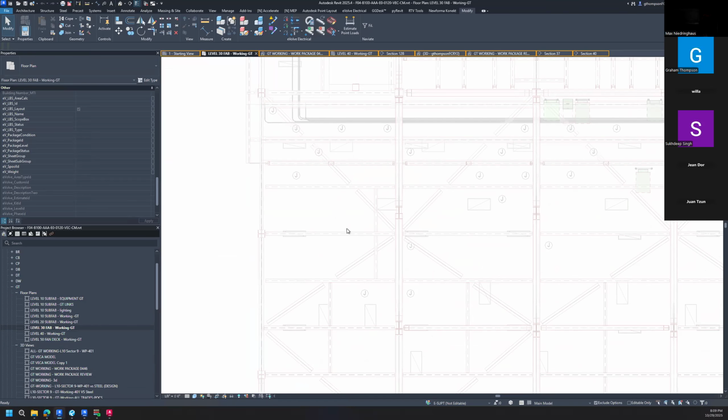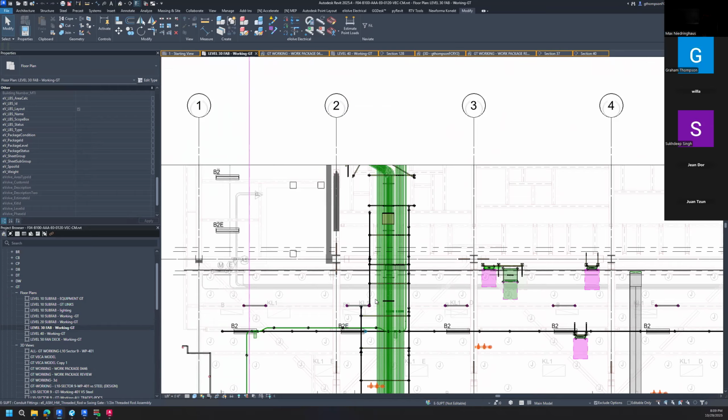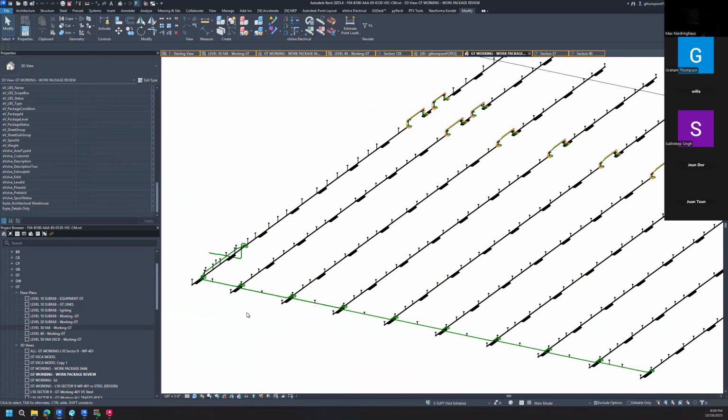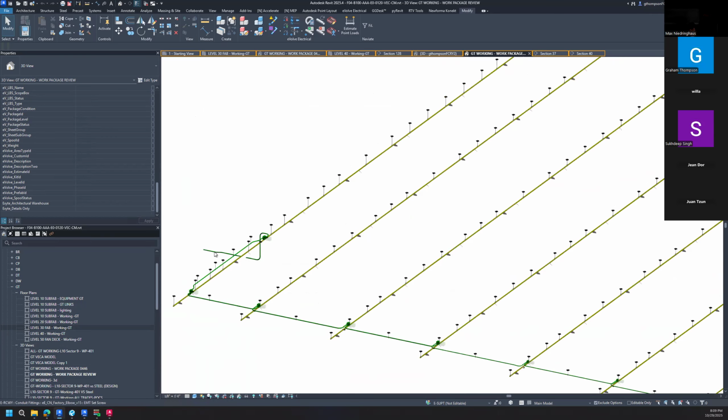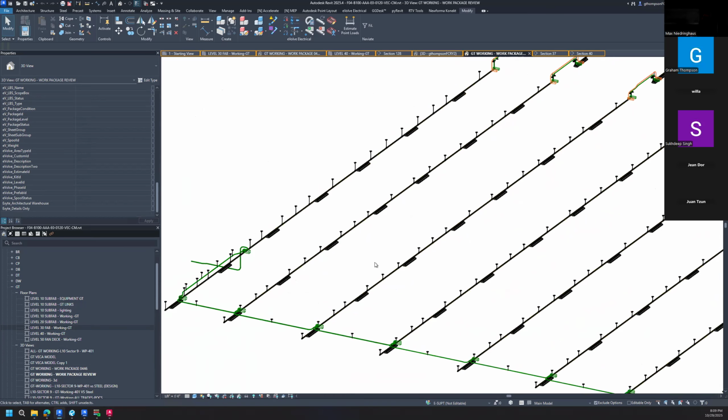And so here's my Revit portion of it. You can see all this in Revit and how it models. We use Revit to model. Navis is just a viewer. All it does is allow us to see things. Everything's just an export. So I'll go to my work package, export this, refresh it in Navis and see what happens. Did that offset move in a location that I'm no longer hitting somebody? And you just keep massaging it until you can get a product that's constructible.